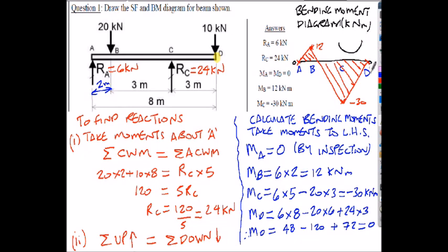You wouldn't be expected to really put this in, but the sign convention would be of this kind of shape, where you've got the bending moments like that. It looks like a smiley face, really. It's an arrow, and that's the positive bending moment notation. Okay, that's for completeness. But the diagram is what you're really interested in labeling. So there should be nice straight lines between the points there. And that's a bit curved, my lines, but they should be straight. And that's it. That's the bending moment calculations done.